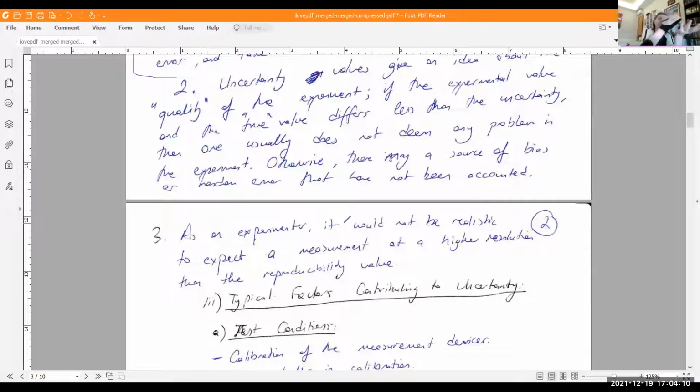In this case, it is not very realistic to try to reduce the error here, or to interfere with your production, because practically 98 and 93 are within the reproducibility limits, since these analyses are conducted at different times on different samples from the same batch of your production. So they are comparable. It is very likely that they come from the same distribution.